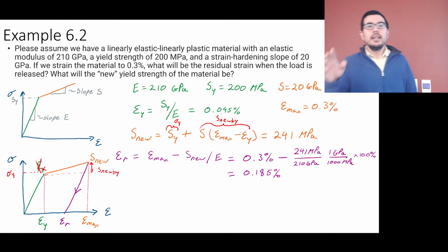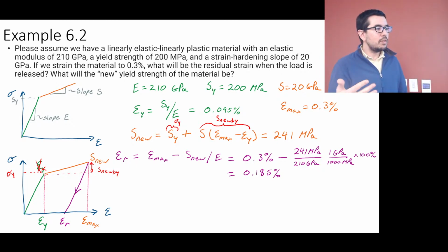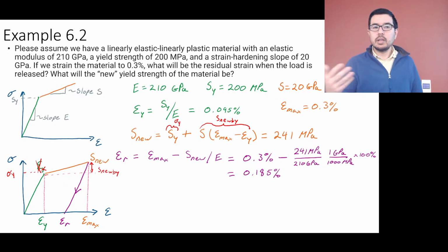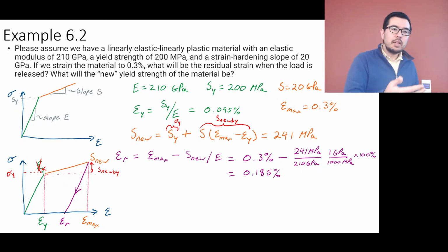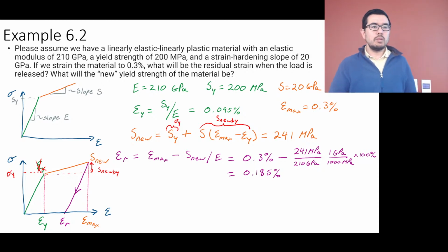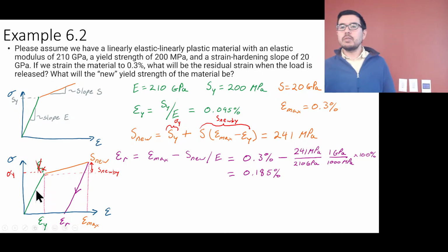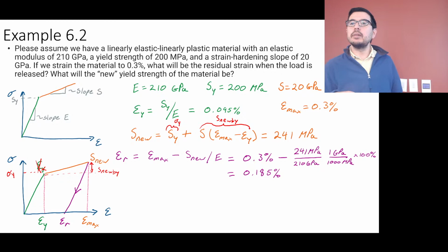If you go compressive and it's a ductile material, then you can assume that the compressive yield strength is going to be about the same as the regular tensile yield strength. You can essentially draw these curves, but backwards, because you'd be going down. You'd be in quadrant 3. We're in quadrant 1 right now, but you would be in quadrant 3.